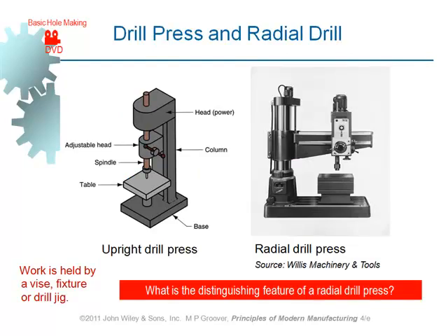Okay. And two typical drill presses which are used in industry. That's a very small size drill press. We've got this type of drill press in the workshop. I don't know if you have seen it. When you go to the workshop, you can see this one. We've got a number of these machines. These are often referred to as sensitive drill presses as well, because the operator puts his arm on the lever and pushes it down, and he senses when the drill bit is cutting through. The force that you need to apply is significantly lower when the hole is completed. So it's called sensitive drill press.